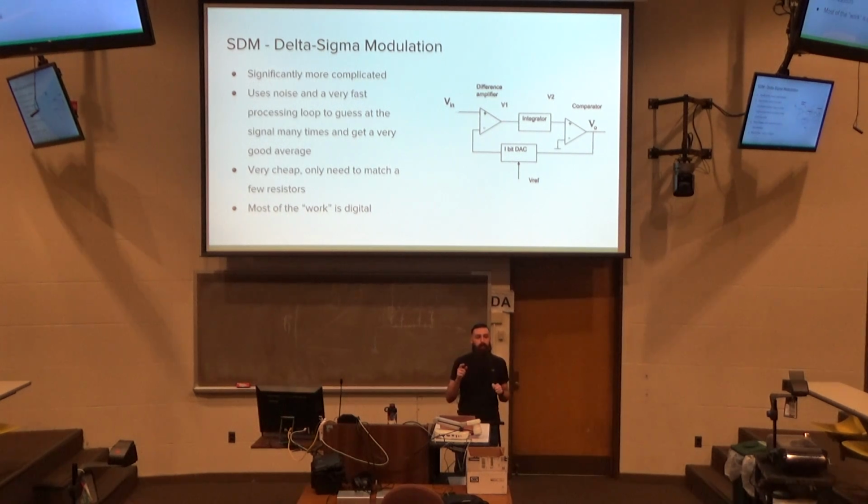The way it does that is by running at a significantly higher speed than the sampling rate, doing something called oversampling. Oversampling is when you have so much time between when you need to output your next change in the wave that you're able to make the approximation, let's say, 40 times. So you're running at 40 times the speed of the sampling rate. If the sampling rate is 44.1 kHz, you're at 40 times that, and you're able to do 40 different approximations to get the best approximation you can, and then output that. You run faster, but for our technology, that's not a problem. We can get a clock rate that high.